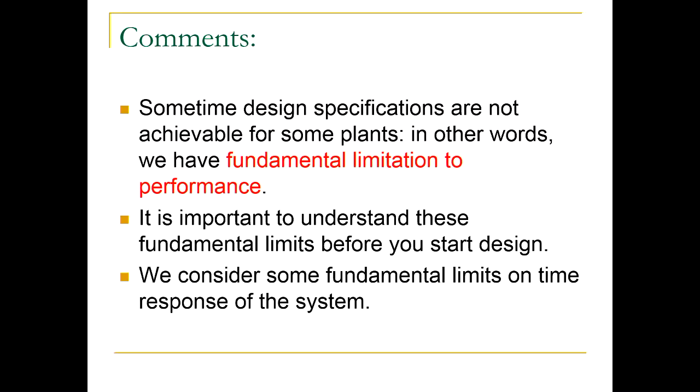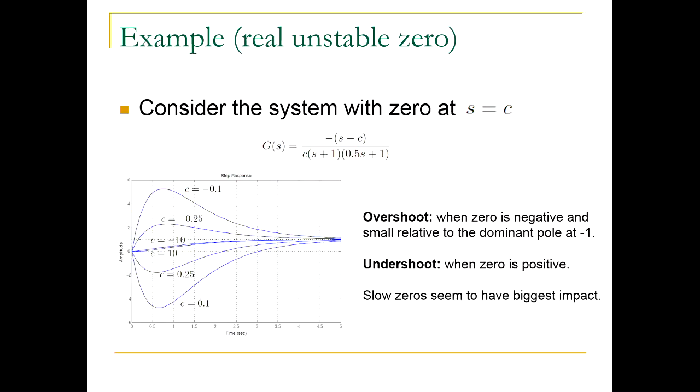Now, what I also mentioned, you may remember, is that transfer function systems that exhibit this sort of thing often have unstable zeros. So unstable zeros in the plant model would force you to have some undershoot. We will now look at this in an example.